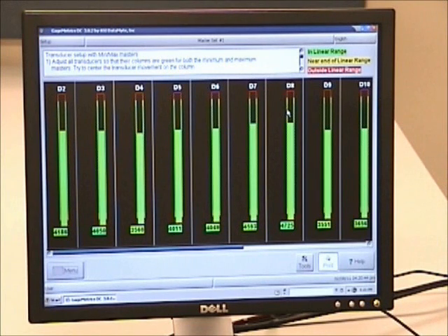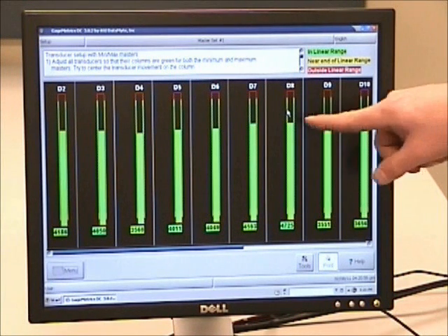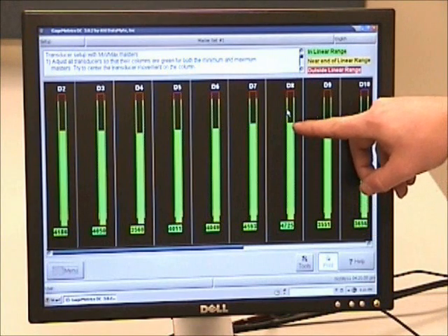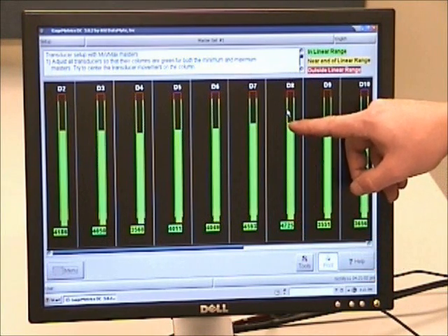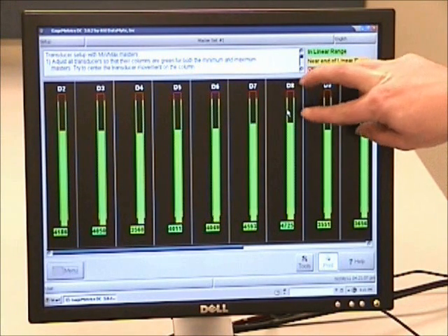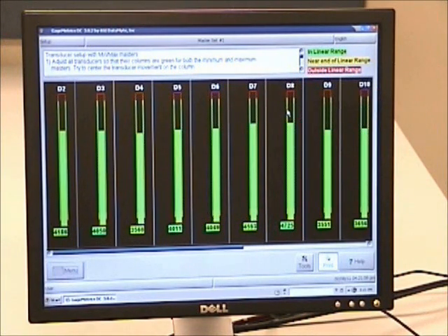their travel. Now I've got these all set, and it's simply as easy as loosening the set screw that holds the transducer in its hole and moving it back and forth while you wait for this to fall in the green area. Of course, I got this set for mostly retract, and this is over travel. But these are 10 millimeter transducers, so you've got nearly 3 millimeters of over travel, more than adequate for this particular part. When this is done, now we can go out to our gauging screen.